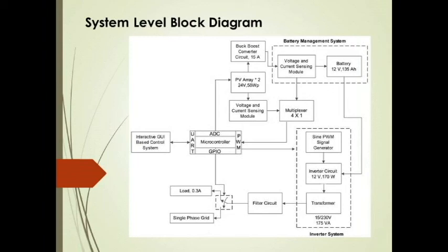This output is filtered and stepped up to 230 volts, which either powers the load or is directly synchronized with the grid. An interactive GUI is designed for the user to monitor and control the system parameters using UART communication protocol of the microcontroller.